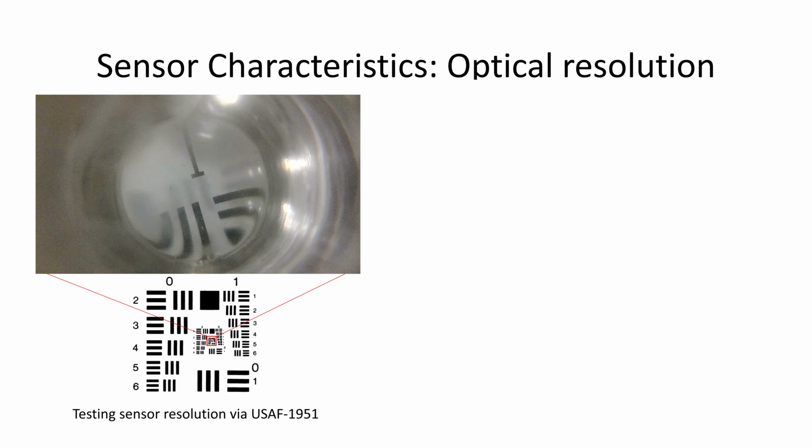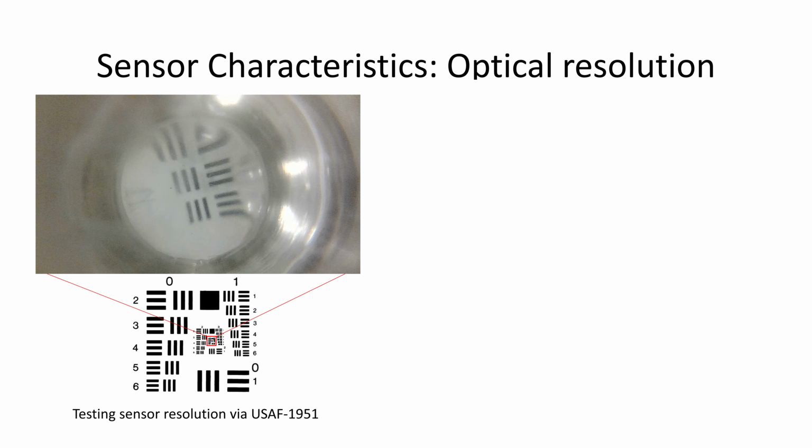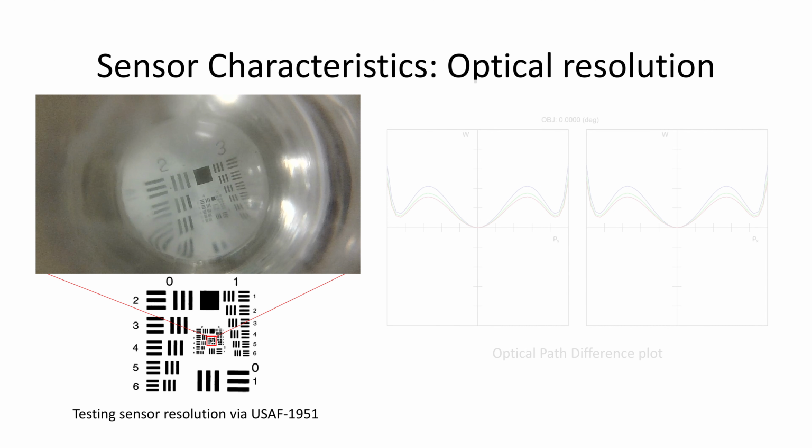Here, we demonstrate the optical characteristics of TacScope. The camera operates within a working distance of 5 to 10 cm, and our custom-designed silicon lens allows it to focus at just 10 mm from the image sensor, ensuring clear tactile imaging. To evaluate resolution, we use the USAF 1951 test target. TacScope successfully differentiates Group 4, Element 2, corresponding to a resolution of 55 microns.